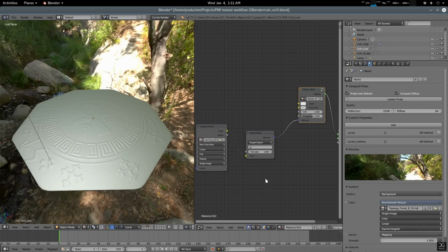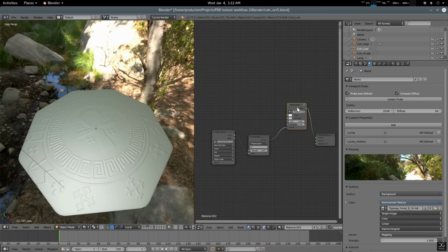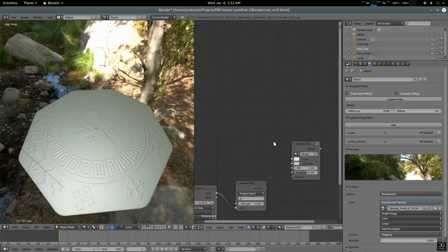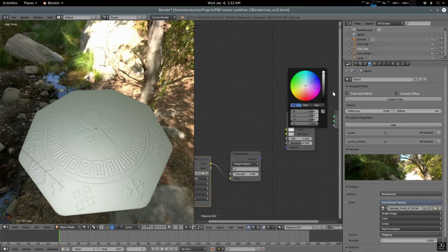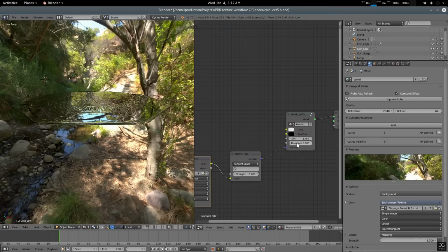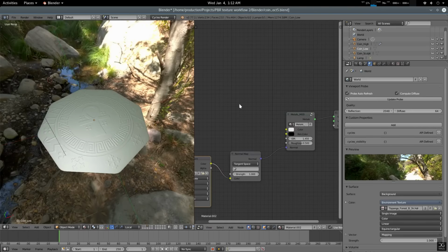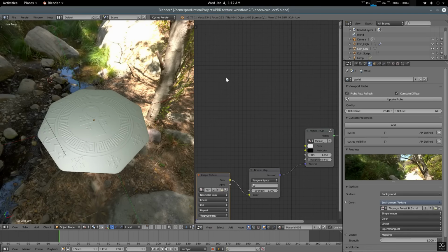So what we need to do here is basically set our mind on how we should use these textures. First of all, there is a metallic color and there is a rim color. I'm going to turn it off because we don't need it. Let's use some roughness. This is actually a pure metal, so increase it, 7.5 for the time being.